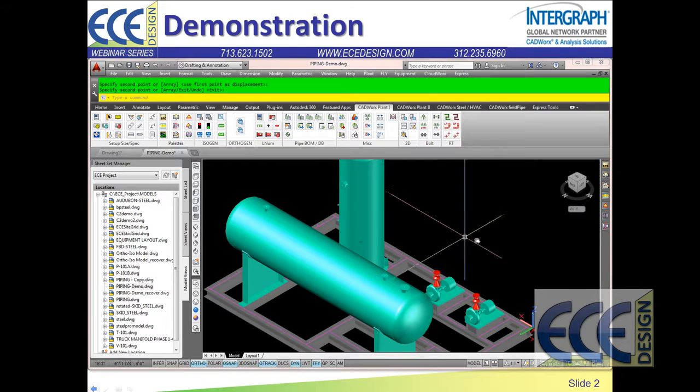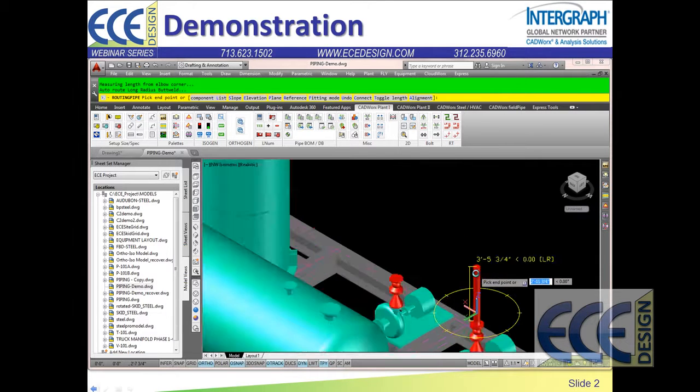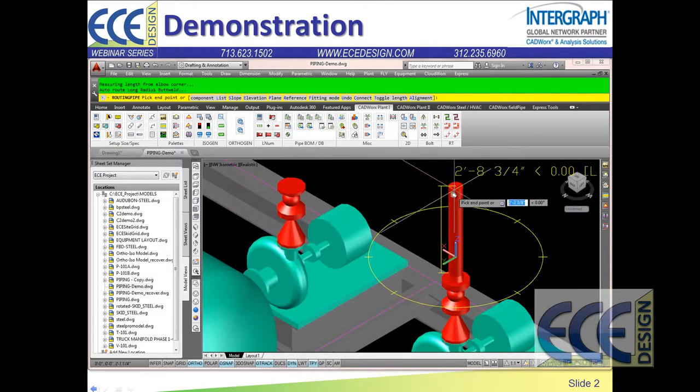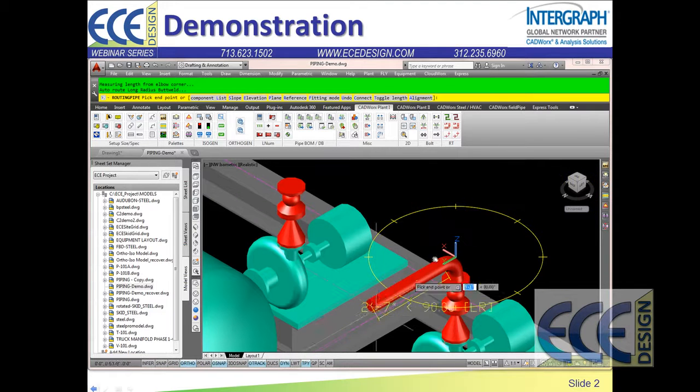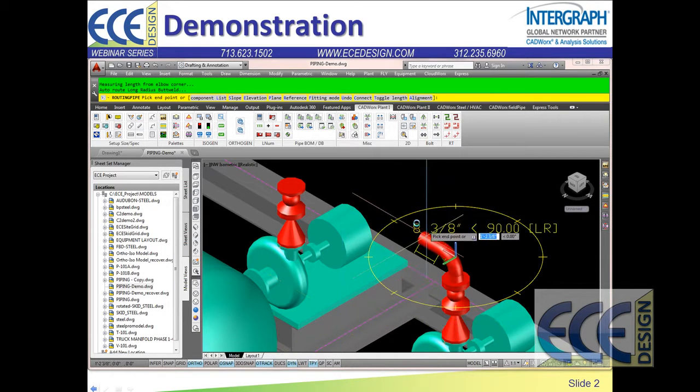This is where things really change, though. In the past, we might run a routing line, a 3D polyline to establish where our piping and elbows were going to go from this point. But in the new system, we have the ability just to simply hit the plus grip, and now we're adding pipe and elbows, and you can see my flange, my bolt set and gasket came in automatically, and the system's waiting for input on which direction to go with my pipe and elbows.